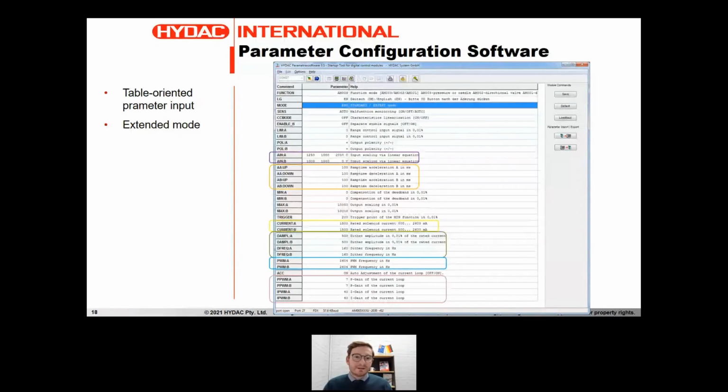The other main thing is you can save these settings and deploy them onto multiple devices. For example, when I removed the device that had those potentiometers at the front with a screwdriver, those become very difficult to repeat. With this type of module, with the digital ones, you can actually just save and copy the settings. So it makes it a lot easier.